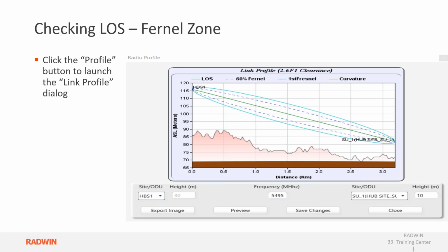I did myself in many countries, even in Africa and Kenya, a non-line of sight solution with the base station with the Jet at 400 meters. It works perfect. The idea is to find the reflection area or the reflection point where you can achieve the link by reflection. But we definitely can cope with non-line of sight, but for short distances, and definitely for near line of sight and vegetation.